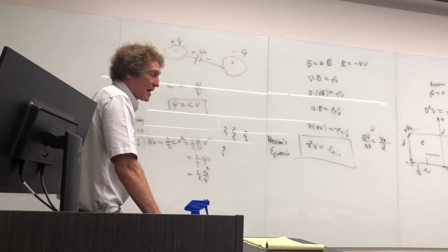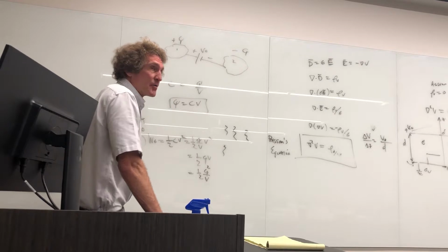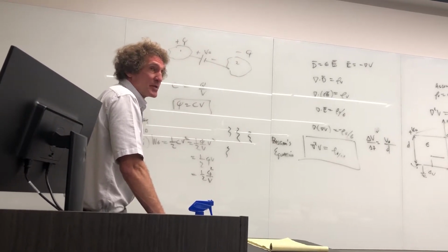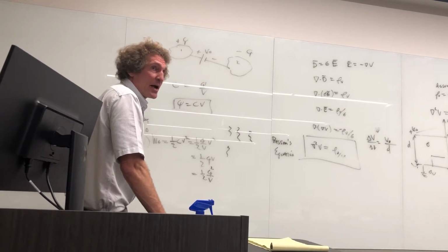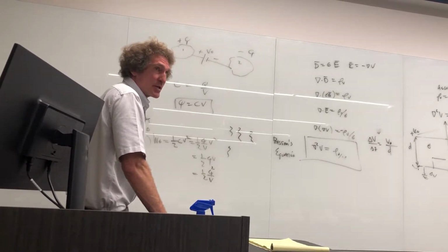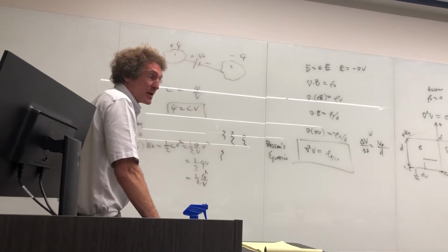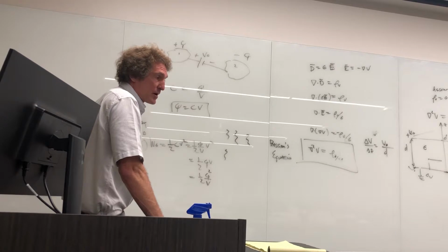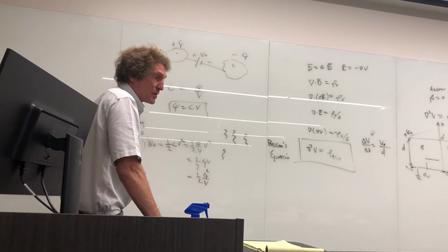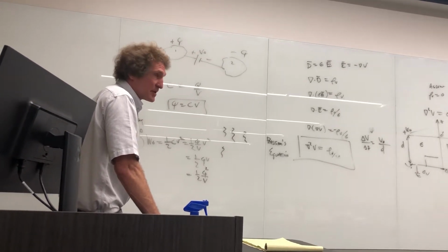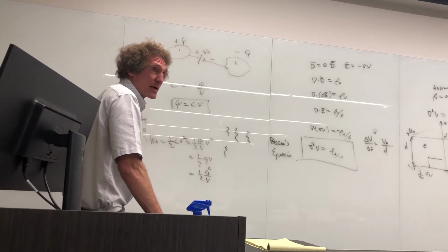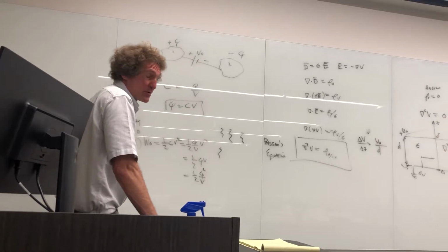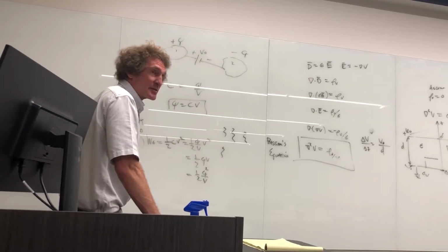So the energy we had was 1/2 times C, 33 times 10 to the minus third, times 10,000 squared, or 10 to the 8th. And we had an enormous amount of joules readily available. When we discharged that into the railgun, we created a current of up to 400 kiloamps just for an instant. That's an enormous amount of current, and the magnetic field was phenomenal. But the thing that always caught me was, our discharge time was maybe less than a millisecond.